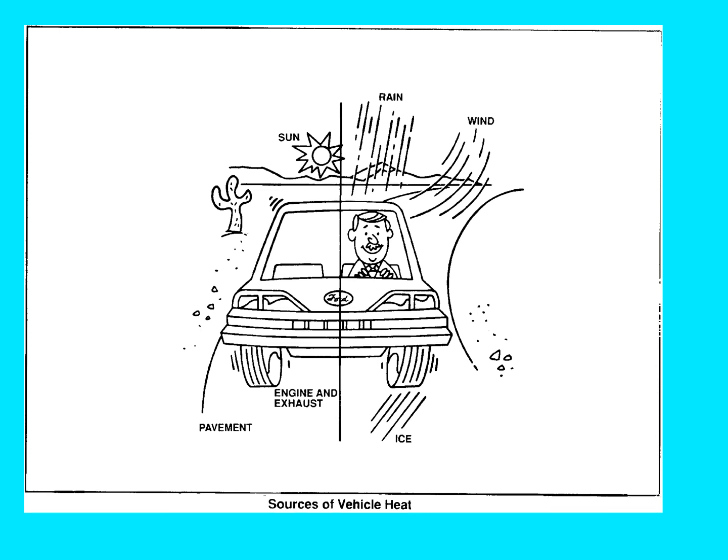So here we are in our very fine, you can see it's a Ford product, and your book that you're using for the textbook is from Ford. It's not outdated other than the refrigerant system that's used. I should say the refrigerant. The refrigerant in that book is R12 and 134A, and R12's been discontinued. 134A is still in use, but there's going to be a new refrigerant that's coming out, or that's being used right now, and that's R1234YF.